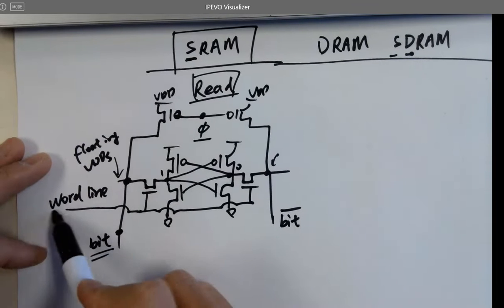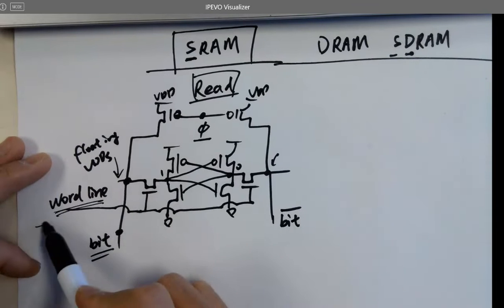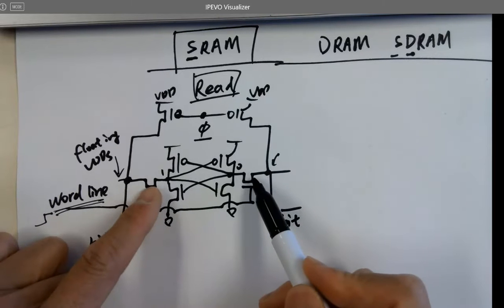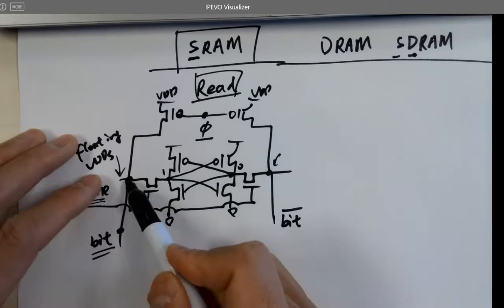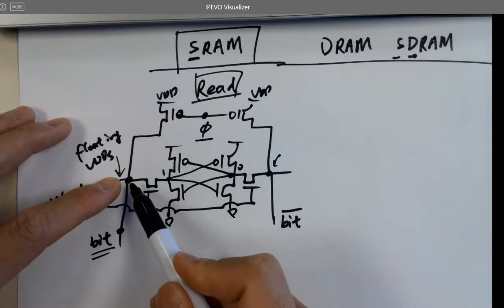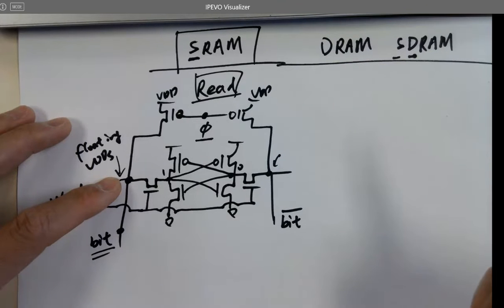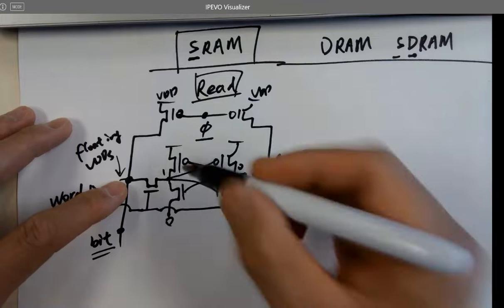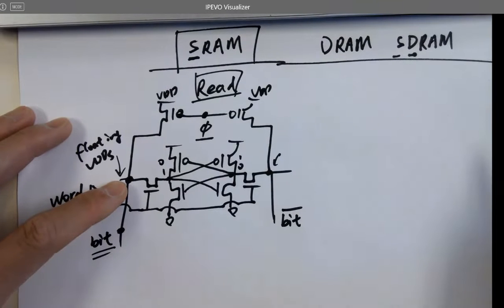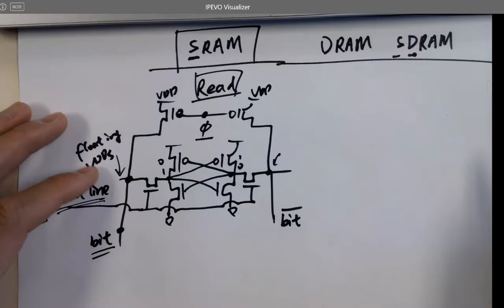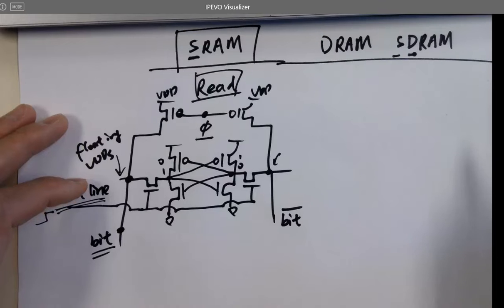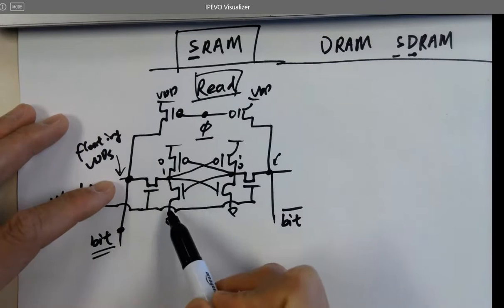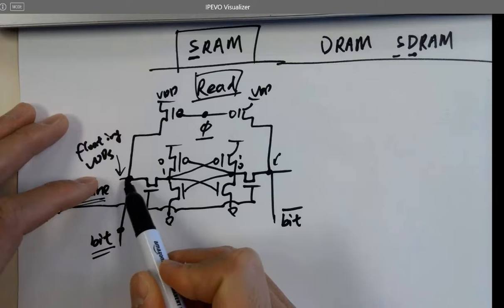If the word line arrives, right, the pulse arrives, it turns on these two NMOSes, turns on these two channels. What I'm reading from here, 1 is not changing. It's got two 1s on the two sides of the NMOS, so it's not changing. What if I have a 0 and 1 here? Yes, it's a strong 0, and it's a floating VDD, so it's going to discharge it.